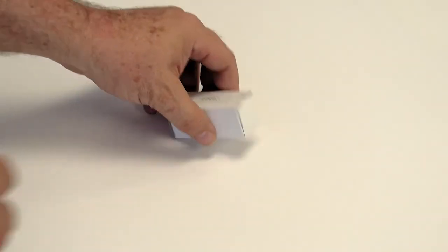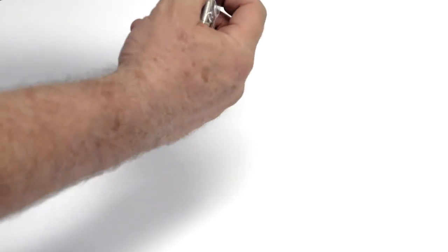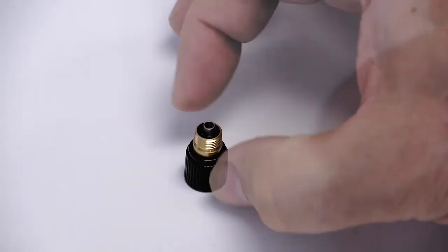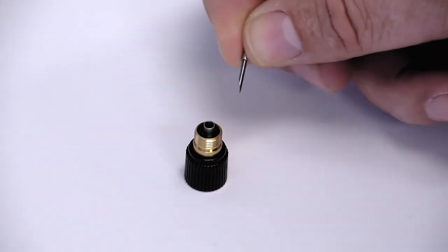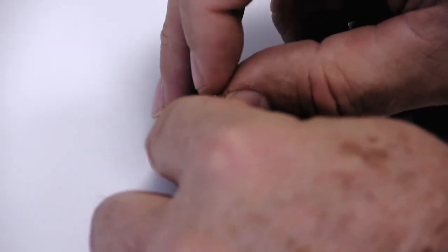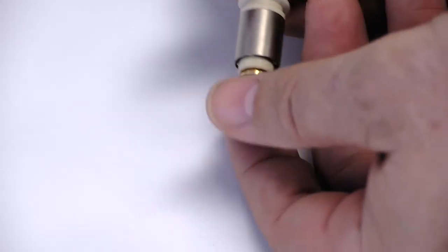Take the blade holder out of the box and remove the cap. Now locate the CB15U blade. Take the blade in hand and insert it into the blade holder cap, inserting the blade tip first. Then mount the cap back onto the blade holder. And then remove the cap, exposing the brass tip.